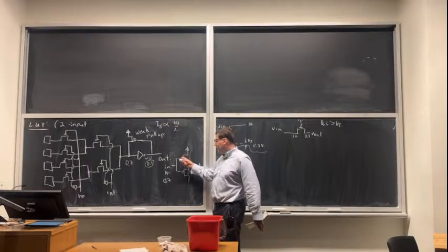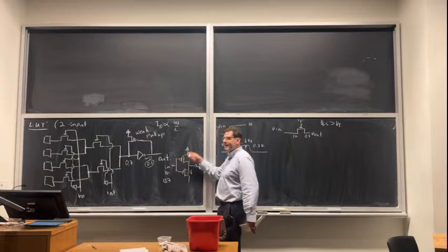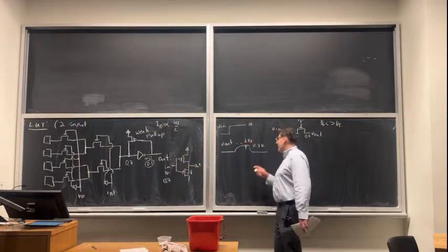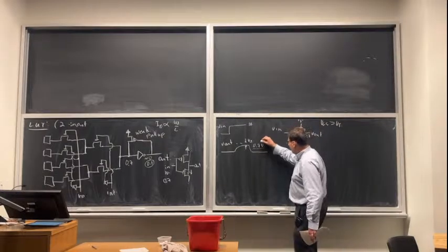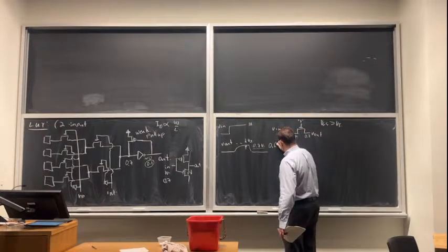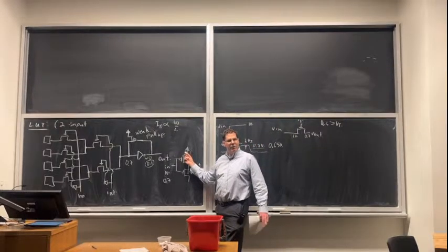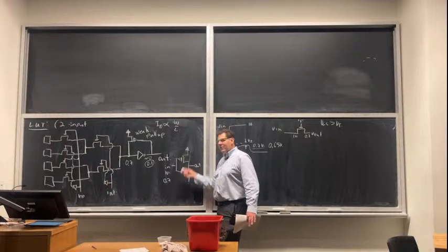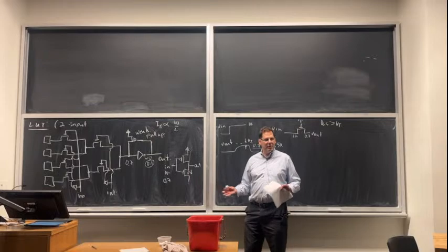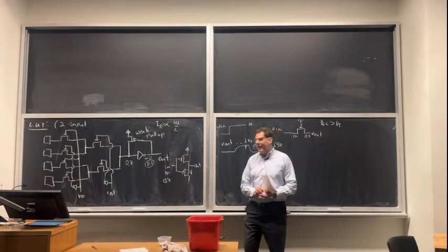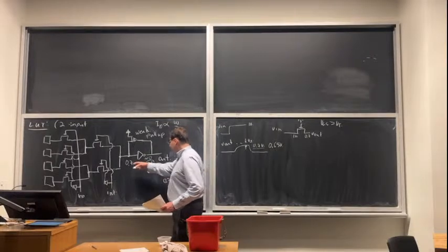It's actually got a VGS of 0.3 volts, which is enough that it's almost on, which means it's leaking like crazy. And it's really sensitive. It turns out that, for some second order effects, this 0.7 might actually only be 0.65, and that means this is truly on, not the strongest on. For one inverter, that's some power. If you multiply that by 5 million inverters, it melts your chip. So you can't do this. You cannot allow this signal to sit at 0.7 volts.